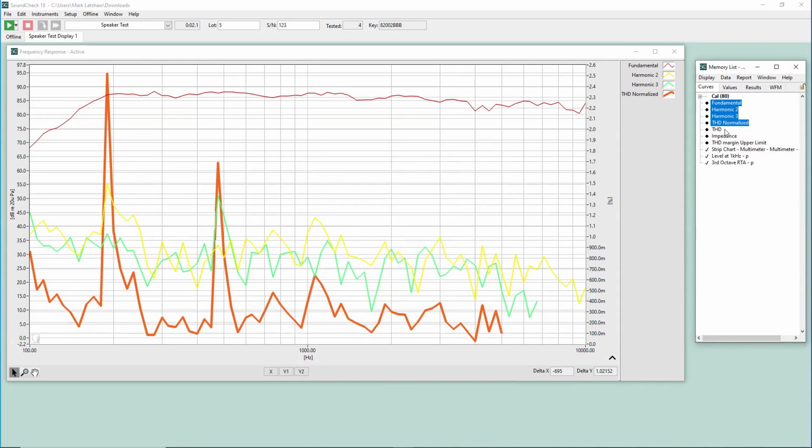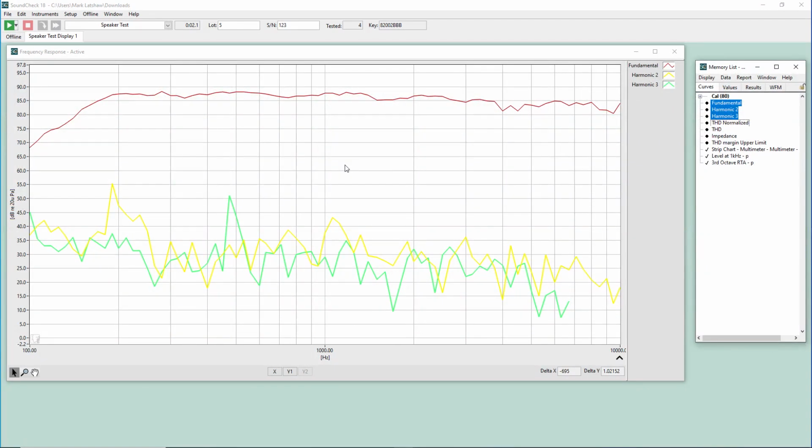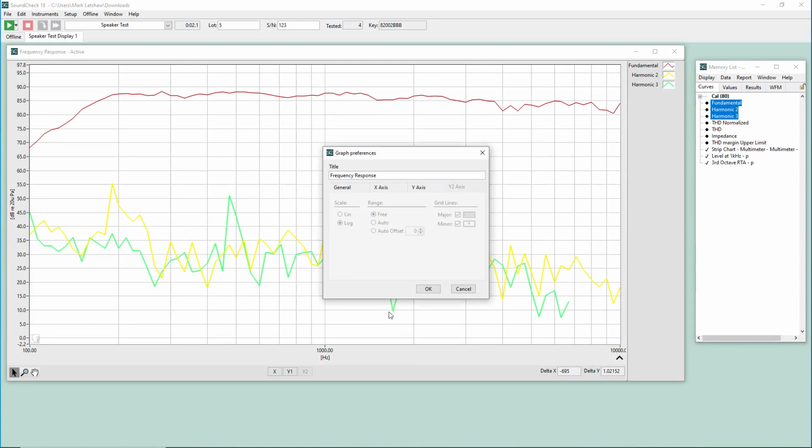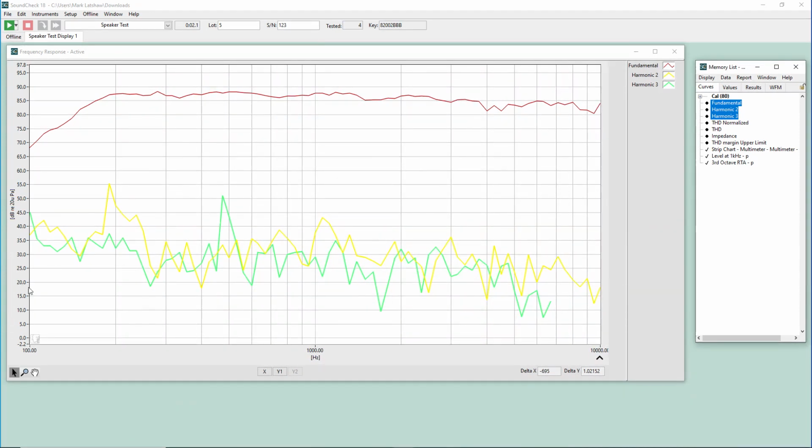Now that we have Auto Offset enabled, let's go back to the X-axis tab. We can see that Standard Axis Ratio is now selectable. With this enabled, it will lock the X and Y aspect ratio. No matter what the size of the graph is changed to, the ratio of the defined y-axis will match a decade on the x-axis.